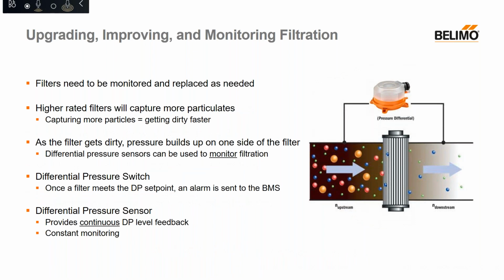Remaining on the topic of filtration, as you can imagine, increasing filtration is also going to increase your maintenance intervals. The higher level a filter is, the more particles it is going to be able to catch and absorb, which means the filter is going to get dirtier quicker and need to be replaced more often. But how do you know when it's time to replace the filter?